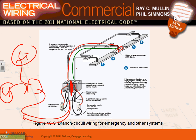The relay senses if the circuit coming from the normal is lost, and it will switch you to the emergency. And you still can control this circuit. This light can be controlled like a normal light. I can turn it on and off because it has a switch. The emergency has no switch. It's not switched at all, it just sits there.